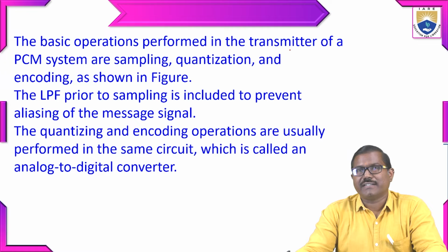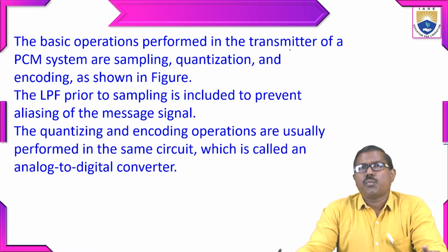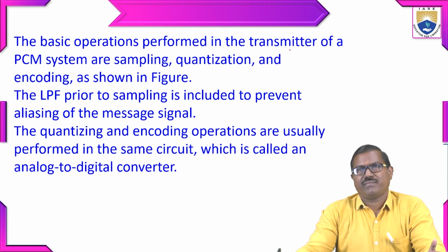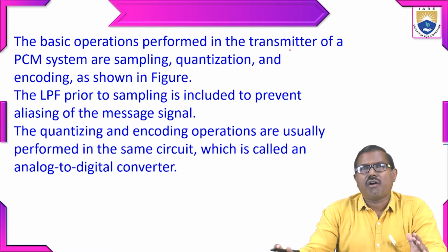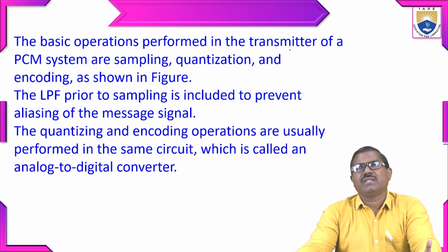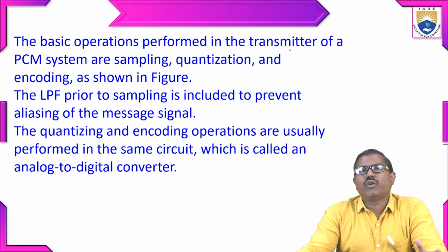Already shown in the figure. So before sampling, we have an LPF, that is a low pass filter. The low pass filter is going to prevent the aliasing effect. So after the LPF we have sampling, so we are going to remove that aliasing.